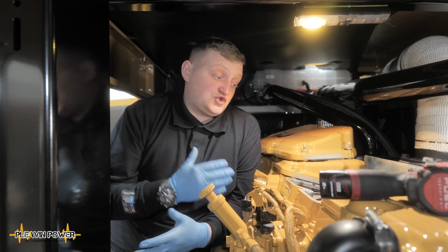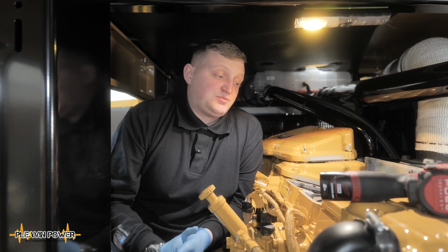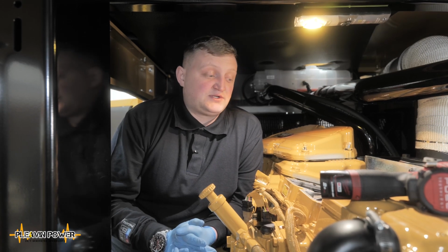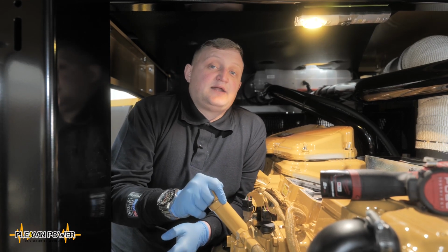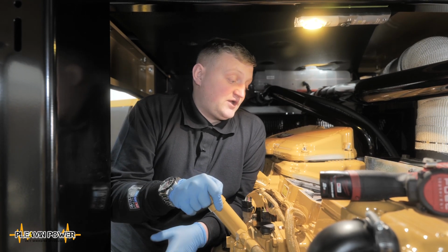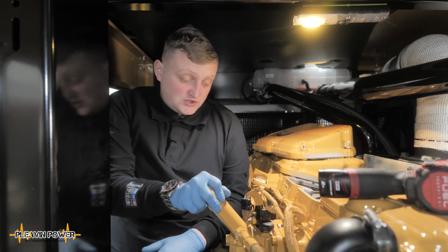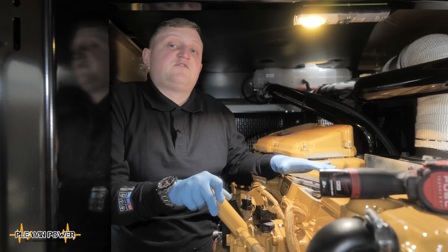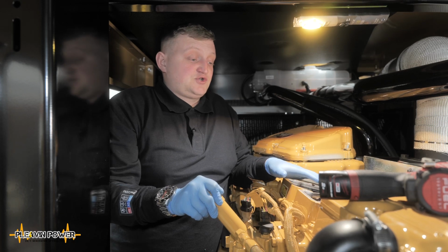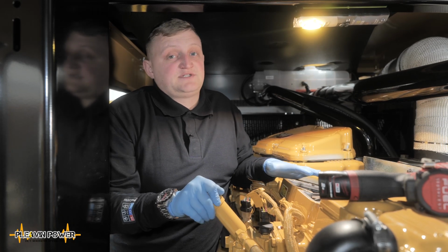If you don't carry out the adjustments, you also won't get any OEM support from the manufacturer, because they'll ask you when this was last carried out and compare it to the running hours of the engine, and then not offer any OEM support at the end of it. So it's a very big and very vital piece of the maintenance regime. You should ensure that this is being completed as part of your SLA agreement with your current provider, because failure to complete the valve lash adjustment means you're not getting a comprehensive service delivery at all.